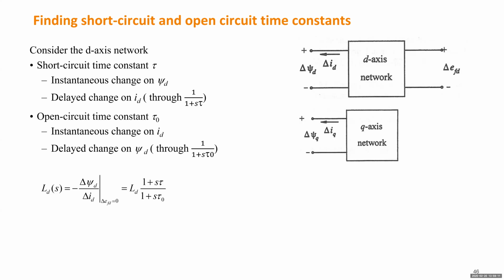So to model how the LD changes with dynamics, it has to satisfy this form. So far, we don't know what that tau is, but it has to meet this condition. Next, okay, this sentence is very important. The time constant tau or tau 0 is equal to the equivalent L divided by R of the effective circuit. Effective circuit means you just pick a single circuit.